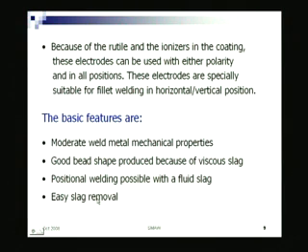Slag removal is also easy, right. This is also an important aspect. After the welding, the slag has to be removed. It should be possible to remove it easily. If you cannot remove it easily, there will be a possibility of small pieces of slag remaining on the weld bead. And if you have to do multi-run welding, that remains entrapped, because solidified slag will not float up. So, slag removal is another aspect which should be looked into while designing the coating.